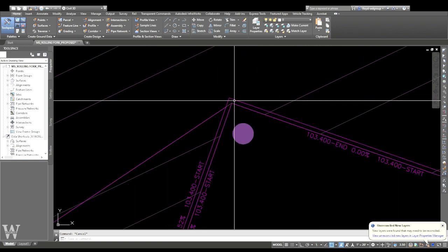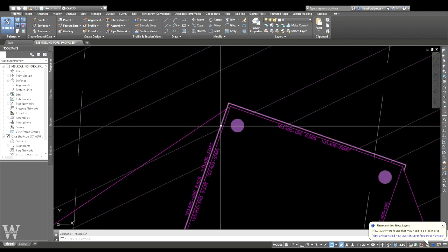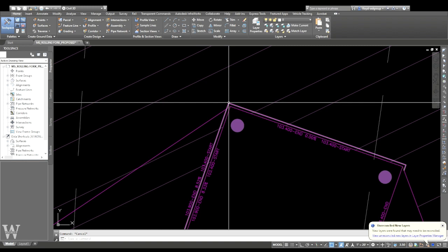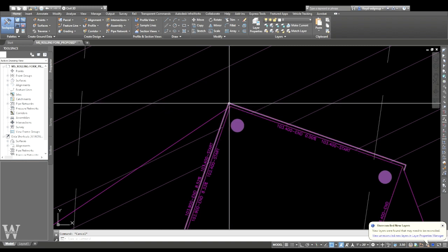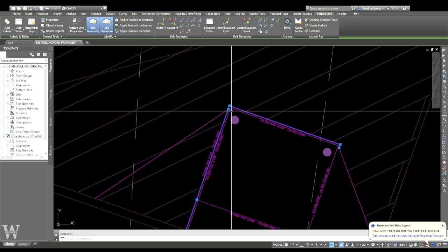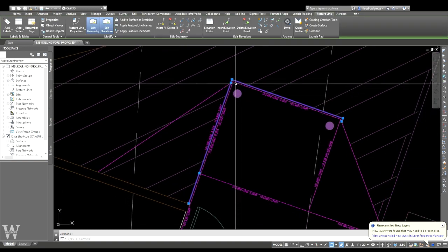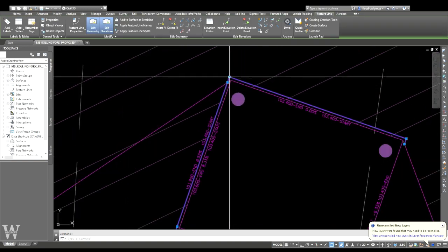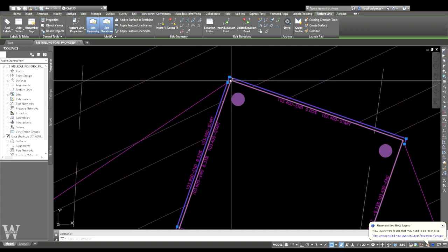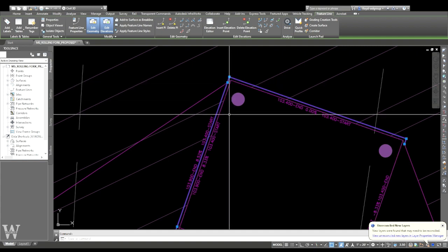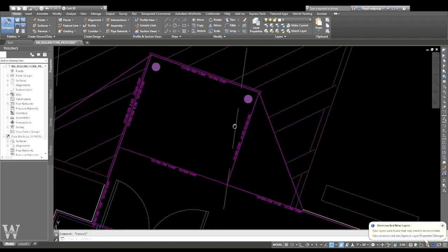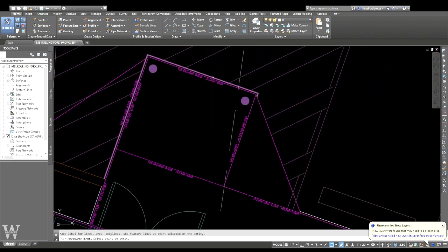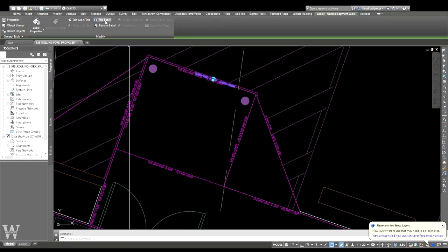Or, okay, I want it to be 8.33 and I calculate all that down there, and then that point's going to be the one in that point, and in reality that point really doesn't exist in the real world. In that place, that point really is right there in the real world. So just don't let that throw you when you go laying out things this way. But that's the way you have to do this. It's the way you have to grade with Civil 3D.